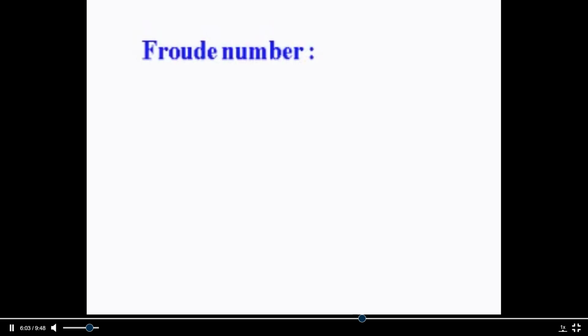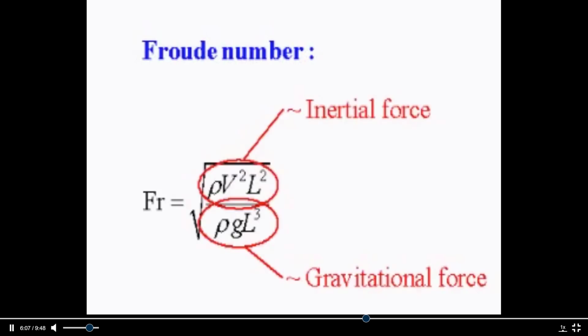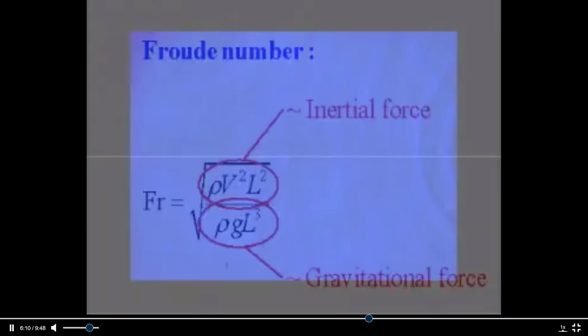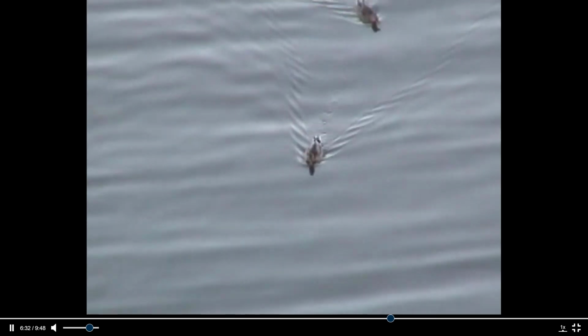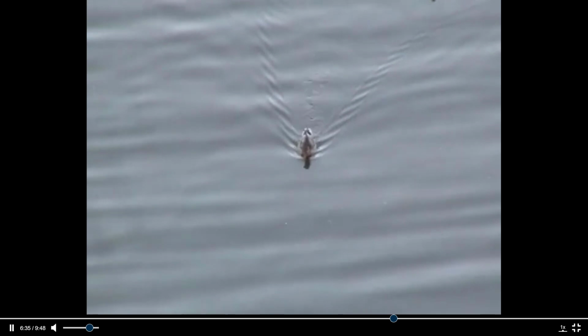In liquid flows with free surfaces, the Froude number compares the speed of motion to the natural speed of gravity waves. A ripple tank demonstrates motion with a Froude number less than 1, equal to 1, and greater than 1. In the last case, surface disturbances are left behind, forming swept-back waves. This duck is swimming at a Froude number greater than 1, producing a similar wave pattern.